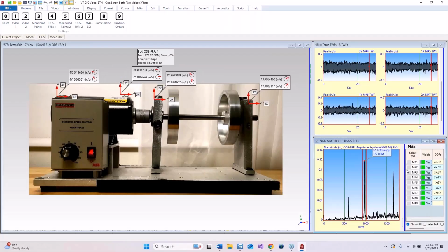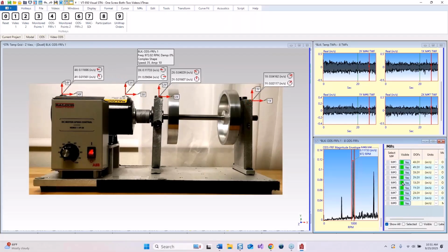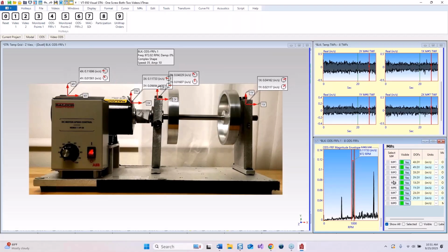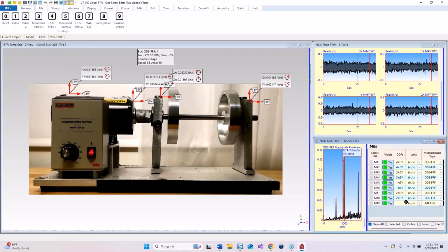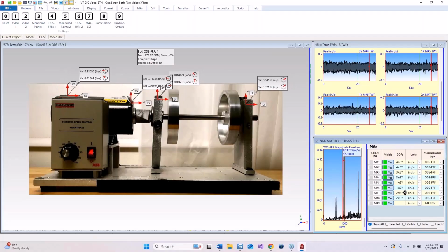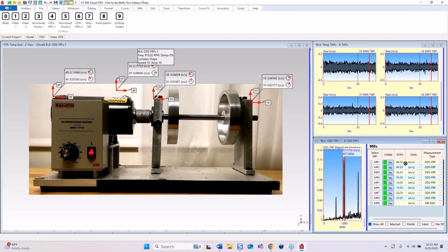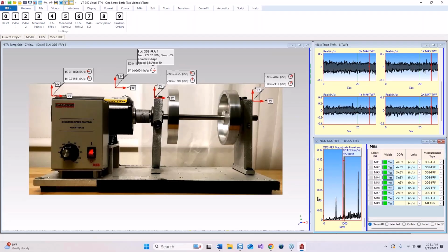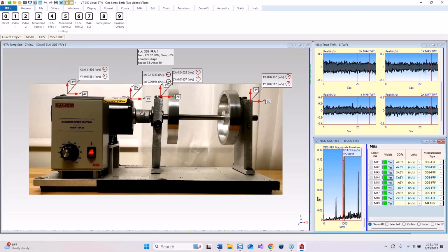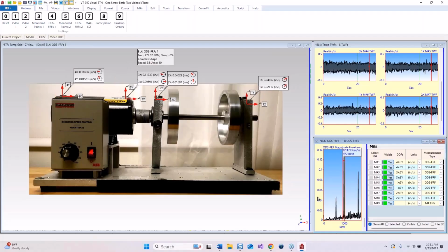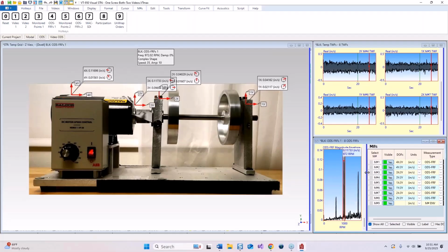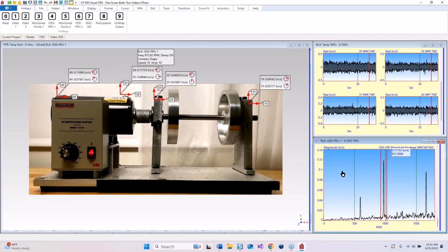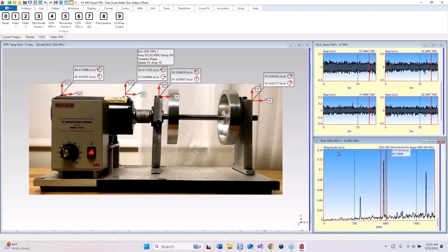If I look in my properties spreadsheet here, you can see I got, well, this 9th one here is an envelope, but I got 8 of them, and you can see they're labeled 1X, 1Y, up to 3, and the reference is 3Y. So same as a cross spectrum. ODS FRF is a little different than a cross spectrum. I can integrate and differentiate ODS FRFs. And these are in units of, let's see, is it saying what units they should? Oh yeah, inches per second.